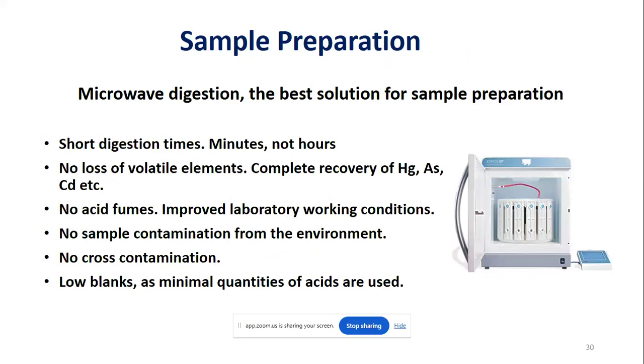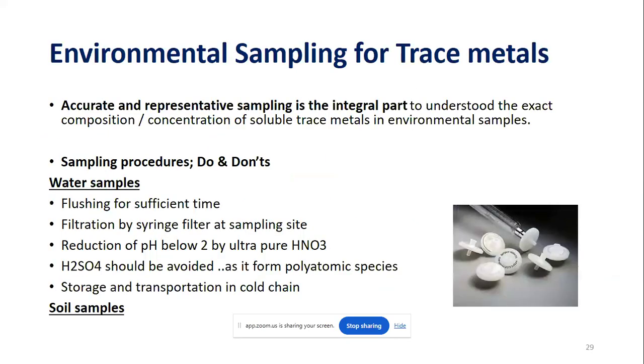Sample preparation is again one of the important aspects when we measure the sample. For the water sample, once we collect the water sample from any place, from surface water or groundwater, we initially filter this water sample through small filter papers. In that case, these are small polymer filtration kits we carry to the field.